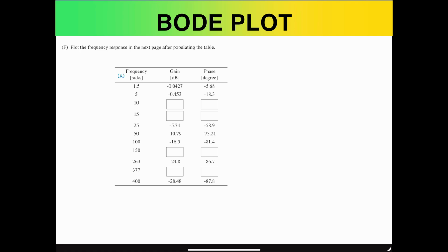So with that, let's rewrite the equation of G(s) that we had in the previous question. So we had 1 over RCS plus 1, and we know that R value is going to be 6.6 kΩ, or 6.6 times 10 to the power of 3, and the capacitor is going to be 10 microfarads, or 10 to the power of minus 6, S plus 1. So if you simplify that, you get 1 over 0.066 S plus 1.